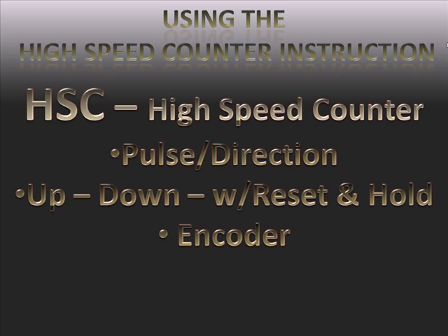The high-speed counter is an actual electronic circuit permanently connected to specific input terminals. When you initiate the high-speed counter instructions, it configures this high-speed counting circuit that is totally independent of the processor's program scan. The high-speed counter instruction can only instruct the counter data type addressed as C5:0 and none other. Once associated with a high-speed counter instruction, C5:0 cannot be used by any other instructions in the program. This instruction actually configures hardware.